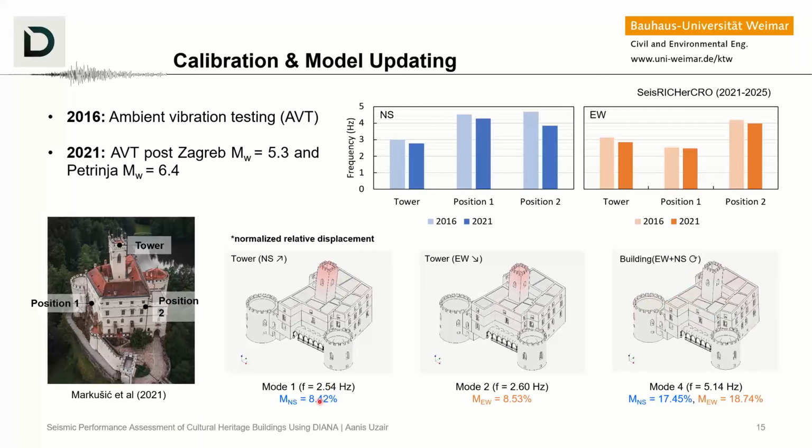Here we have 2.54. A perfect match is most of the time never possible because with large structures and with heavy masses, it is not really possible most of the time to calibrate the model in a way where the dynamic response is 100% captured in all directions. That's why we make a sacrifice always by looking at the error and saying that, okay, a 10% error or maybe a 15% error is an acceptable error for a particular case study.